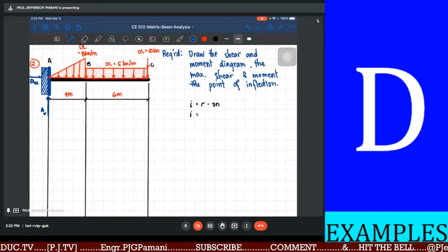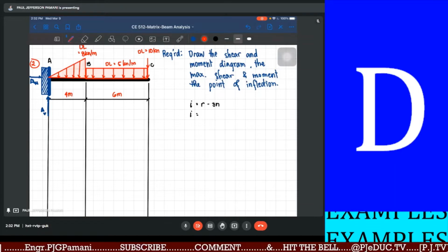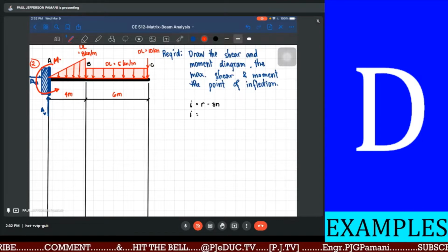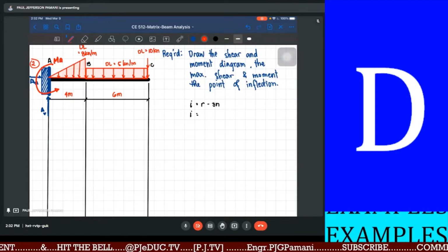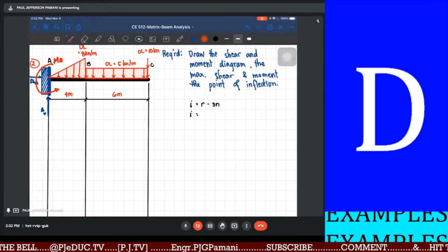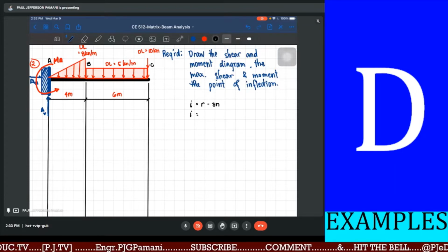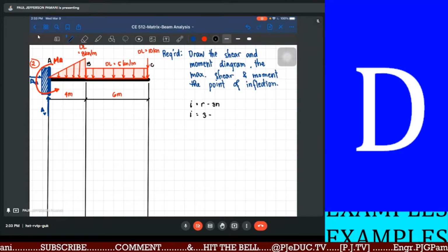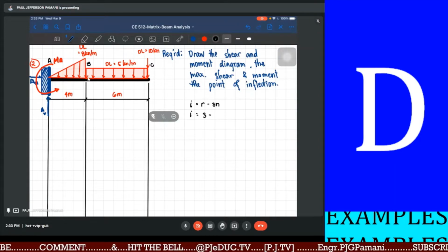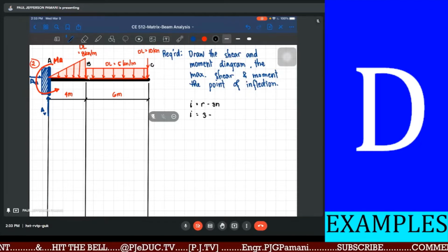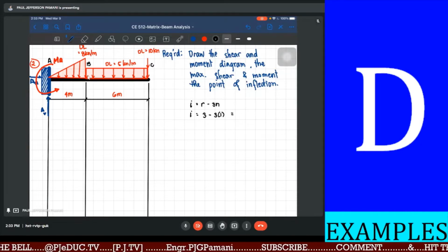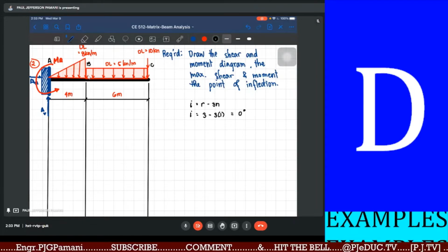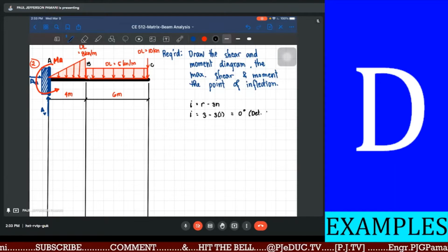We will then verify the bending moment if it is clockwise or counterclockwise. But for now, we'll have to assume it as counterclockwise moment at A. Okay? So we have there 3 reactions. How many parts or how many beam section do we have? So we have only one part for this particular cantilever beam. So again, that is 3 minus 3 times 1 gives us 0 or a 0 degree of determinacy. Basically, this is now a determinate beam.